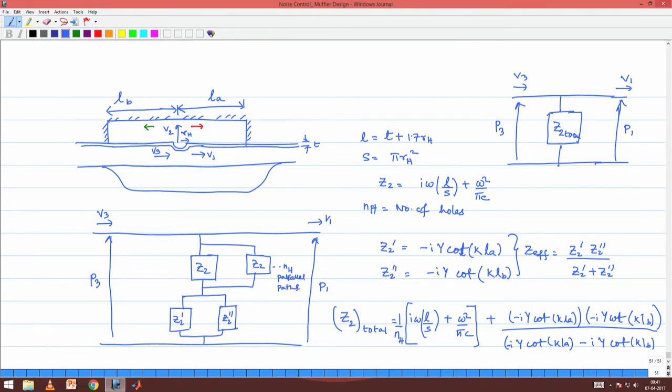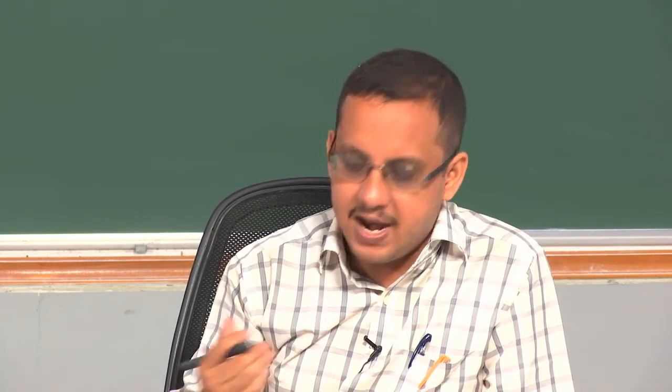But after the sound emerges from the hole, it will see the same impedance, because in the concentric cavity nothing has changed, right. What we did is that we first introduced one hole, and then we said if there are multiple holes at the same station, we are not saying there are other holes at a different station, but at the same location, it will provide more parallel paths.